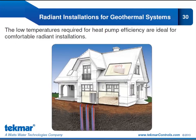So radiant installations are perfectly suited for geothermal systems. Heat pumps operate at their highest efficiencies when the entering load water temperature is low in heating mode. And radiant installations also provide optimum comfort when the water temperatures are low as well. So the two really are a perfect pairing. Now Tecmar has developed control features that further optimize this performance, and we'll cover those as we continue in this course.